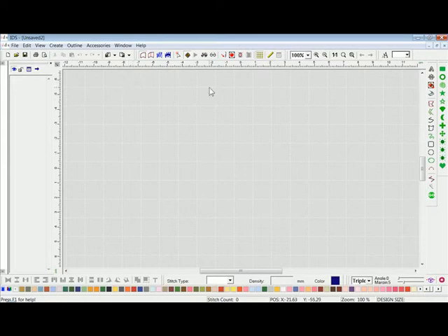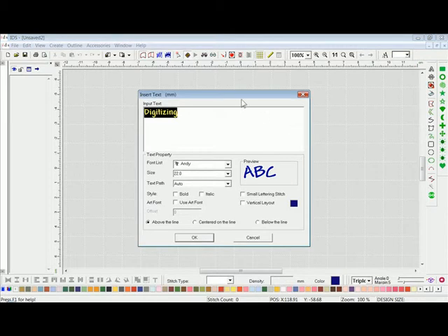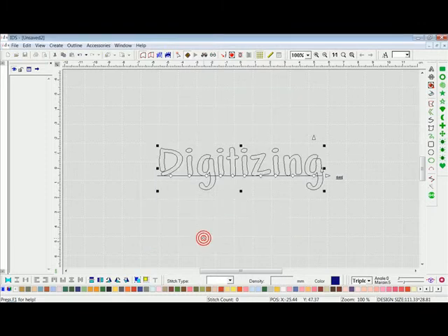To insert text on the right-hand side, we will click on the Insert Text icon, the first icon on the Create toolbar. When we left-click on that, it will automatically input the last thing that we input for the insert text. We'll leave everything as is except for the text path itself. We're going to change the auto text path from auto to line. With this option here, once we press OK, our cursor will turn into a crosshair.